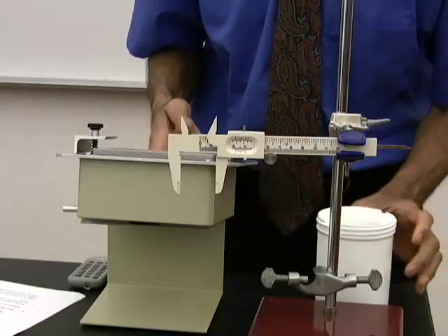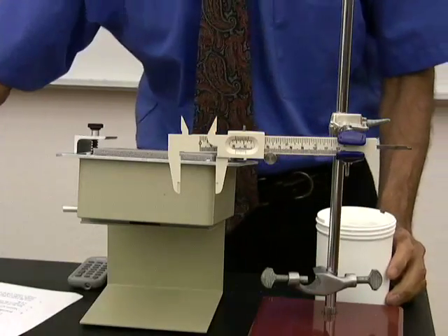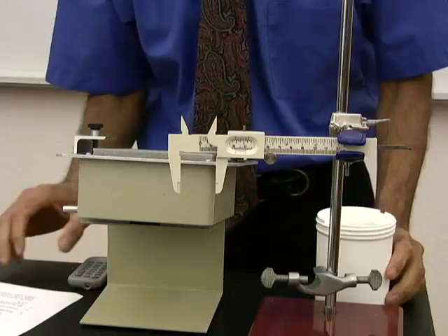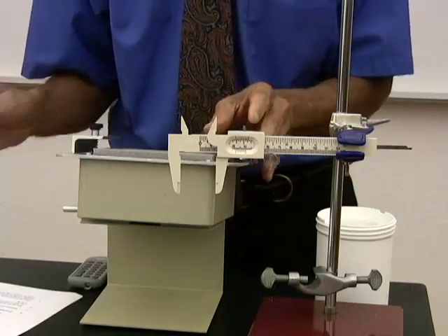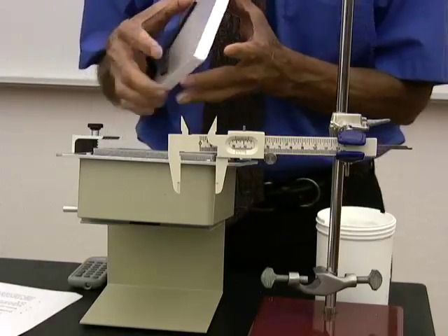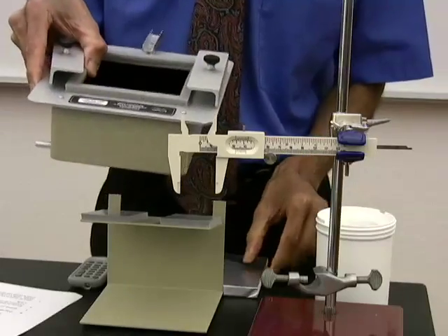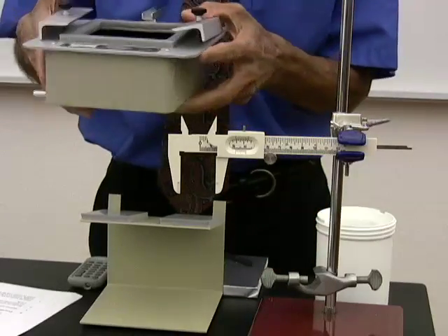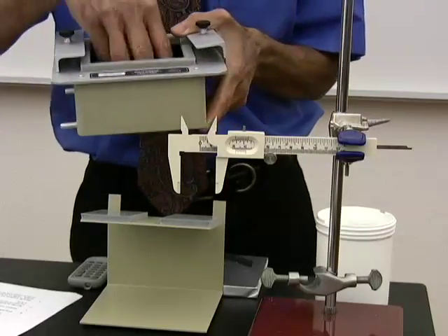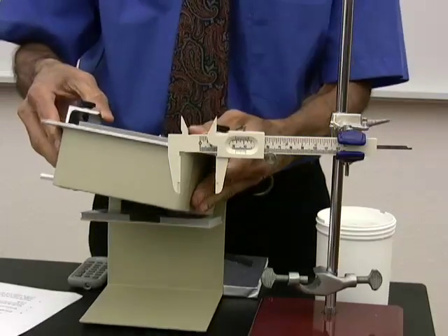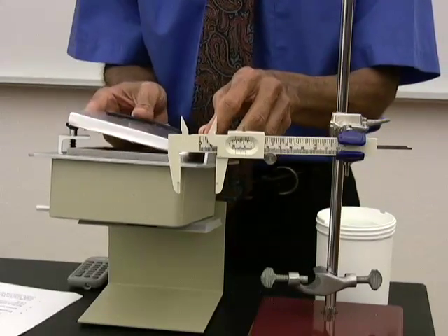Let's now read the method of the experiment. Procedure: measure and record the thickness of the material, delta X, which we already finished. Now let's start with the masonite and look at the equipment we are going to use. This is the steam chamber. I will let steam go into this and out. So inside there will be steam, and we will keep the material in here.